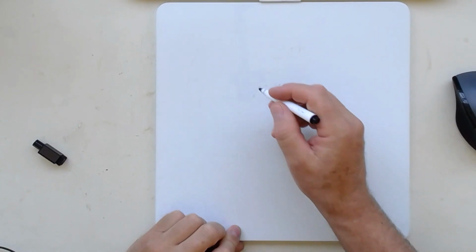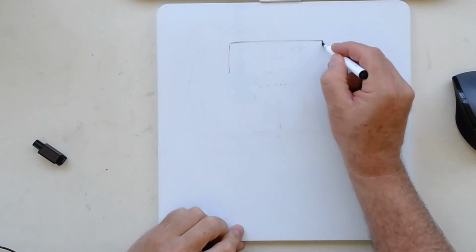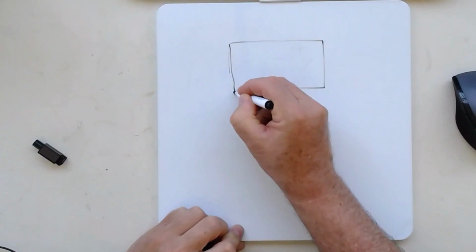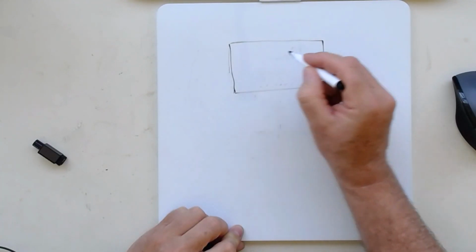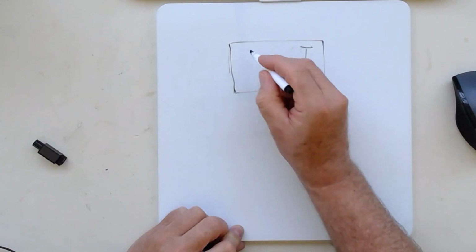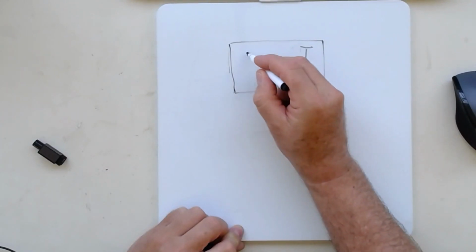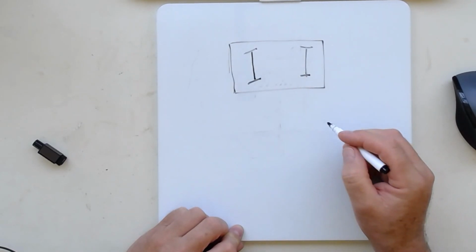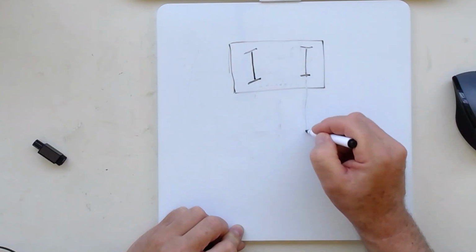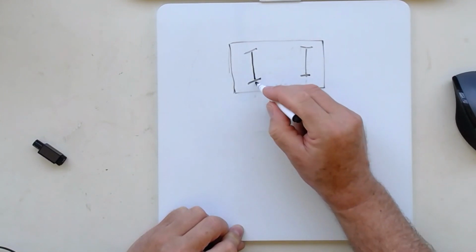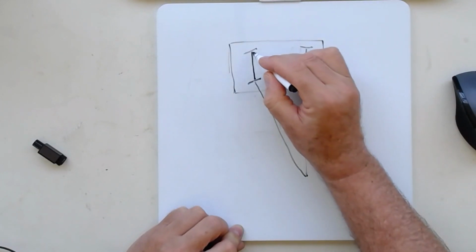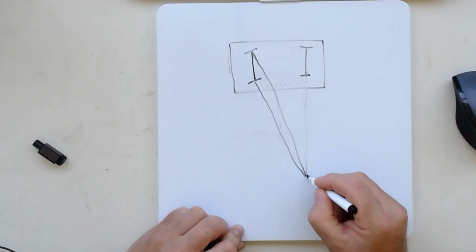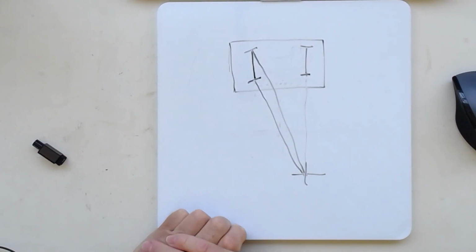So let's look at steering in a little more detail. We'll look at some of the geometry. Let's just say we've got our four-wheel vehicle with two-wheel steering. What you really want to do, I can project that line there, I can project a perpendicular there, and a perpendicular here. They all meet at one point. That's your turning point. What it means is there's no scrub on any of the tyres, and everything's happy making the turn.